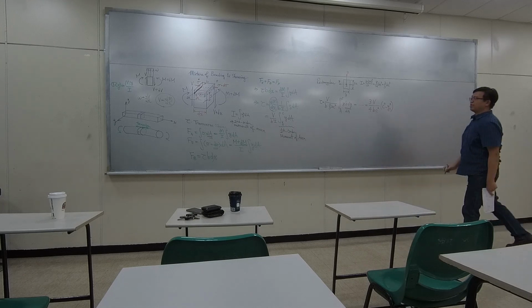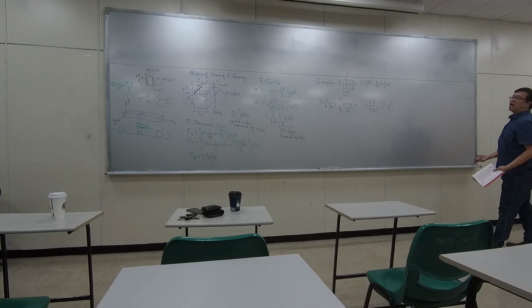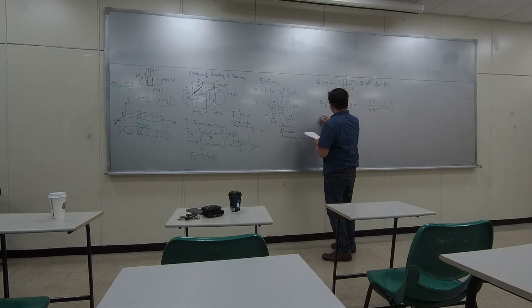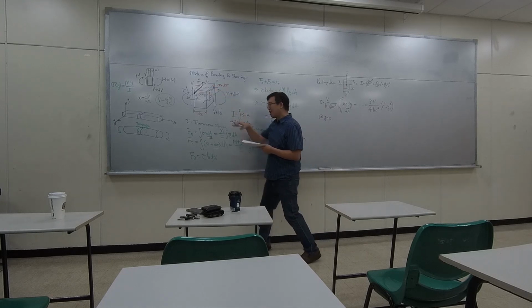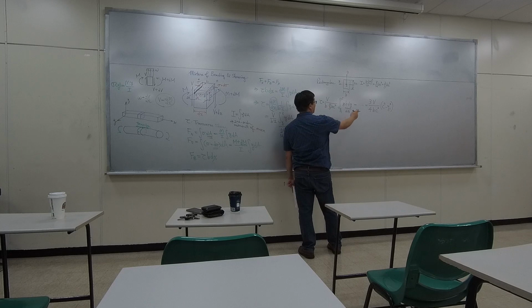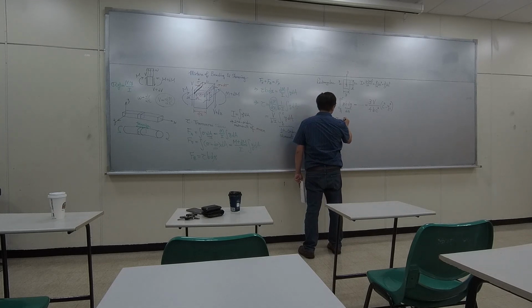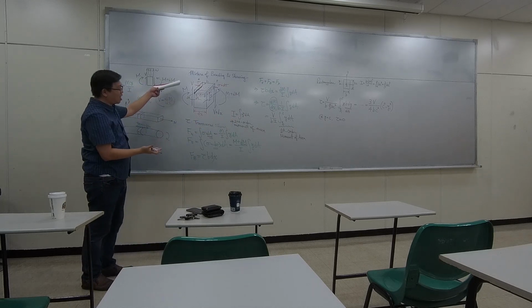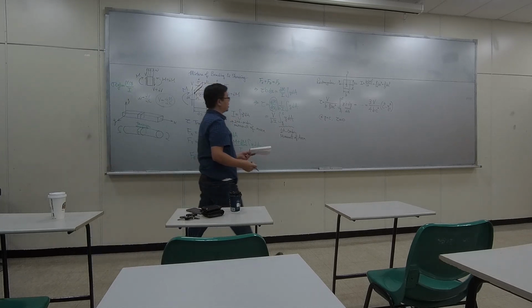That would be the final equation. But where y1 equals c, that's the position at the very top, you realize c squared minus c squared over there. So the transverse shear is 0 at the very top, based on how we calculate this.